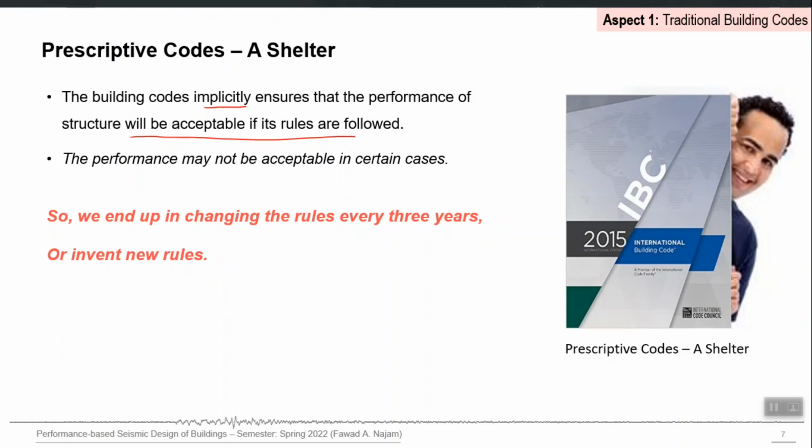If it says that a particular distance or a particular spacing between these two bars shouldn't be more than 4 inch, shouldn't be less than 4 inch, let us say, you have to follow that in its true letter, right. And it is expected that if you follow that, you will be ending in a safe design. So, the performance of the building is ensured implicitly and there is no explicit check.